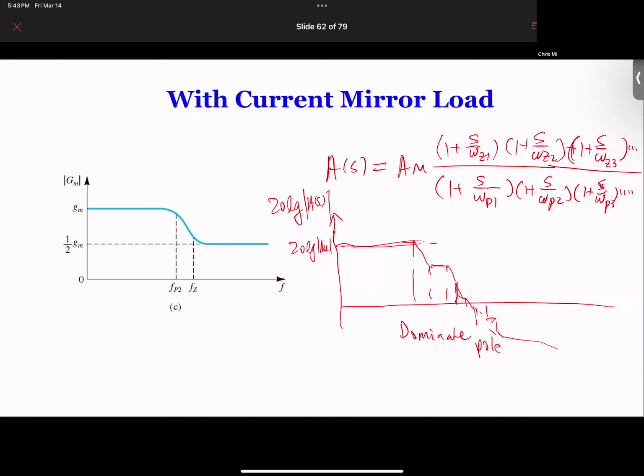But with the feedback, it's possible that resonance starts to happen at this frequency. Instead of the signal getting attenuated, because the feedback makes it so strong, that signal gets amplified. It amplifies so much that it's even more than your actual useful signal. So now you have trouble. You don't even know which one you get, because the one that you want is not even larger than the one that you don't want.